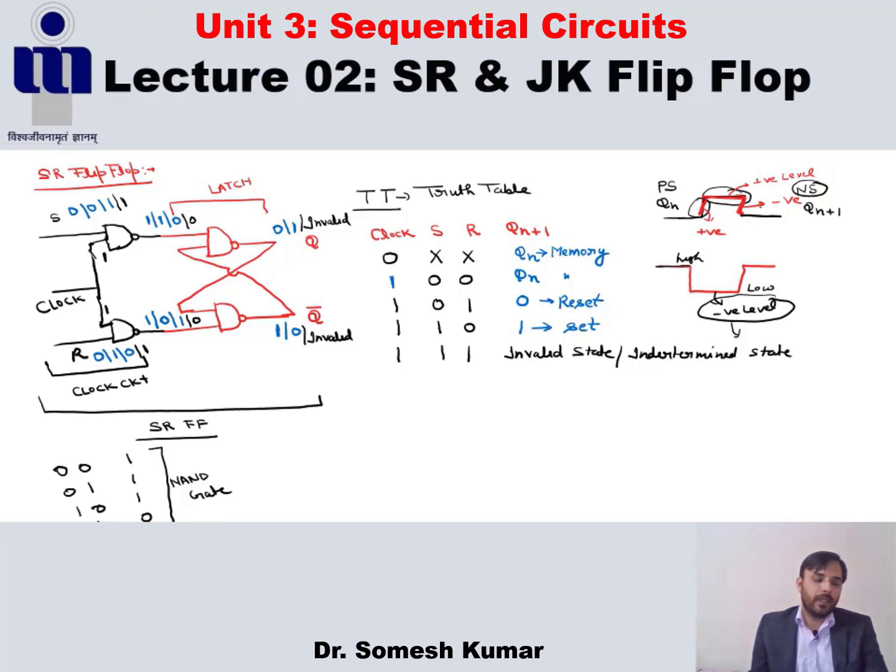Fine. So next is how to design this SR flip-flop with the help of our NOR latch. What is the other difference between SR flip-flop and the SR latch? In the SR latch, if we design it with NAND and NOR gates, it gives two different truth tables, while the SR flip-flops, if we design with the NAND latch or NOR latch, give the same truth tables.